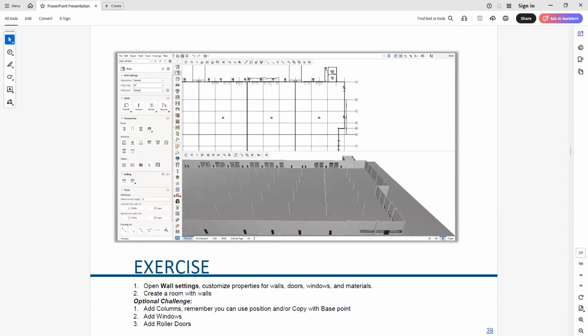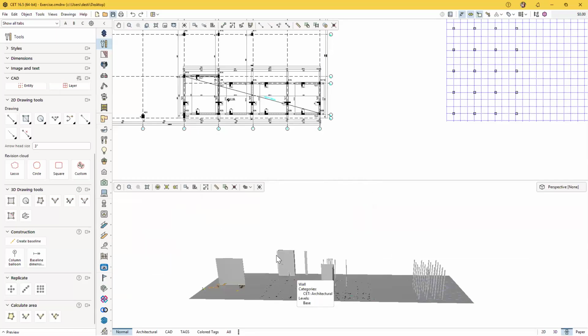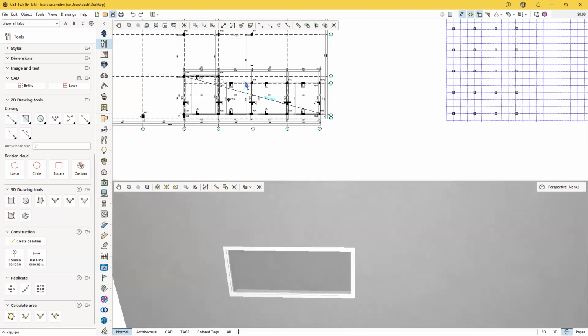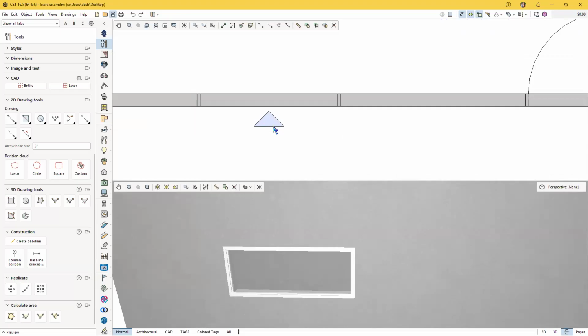So when you're placing walls in your drawing, you're actually going to get that trim on both sides of the wall. So it's going to come in, they're going to be the same, interior or exterior. For the windows, there is a kind of designation for interior versus exterior, and that's going to be this little blue triangle that's next to your windows.